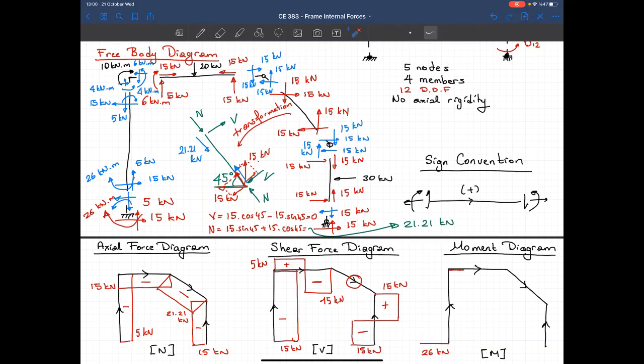Variation, shear force, I have a constant shear force. It means that I have a linear variation in the moment. So let's draw it. This is plus, minus, and 4 kilonewton meters is the magnitude of that moment.